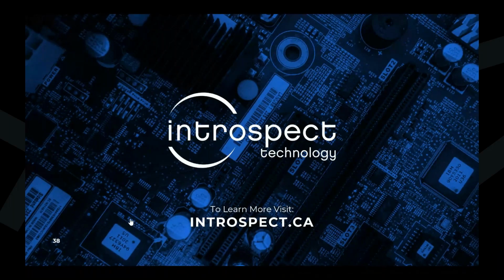the active probes is one thing, and then the analog front end is our own custom analog front end. And inside there's basically custom circuitry for source synchronous tracking and capturing the signals so that we can get all the CA and the DQ signals relative to either the CK or the WCK. So it's really a proprietary solution. It's not an FPGA solution.